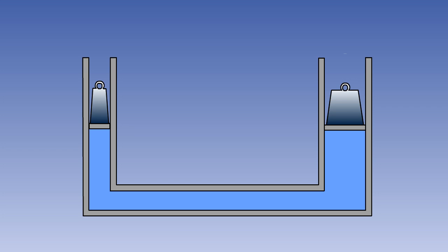Pressure is a property of the system, not the pistons, and is therefore experienced equally by each piston. Because each piston has a different surface area, the force exerted by each piston will be different, even though the pressure is the same. Although in our example the pistons are close together, this does not need to be the case. The interconnecting pipe can be as long as required, and ignoring friction, it will have no effect on the system.